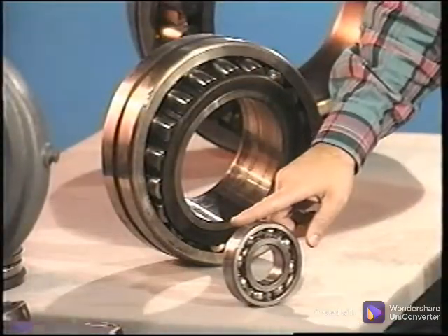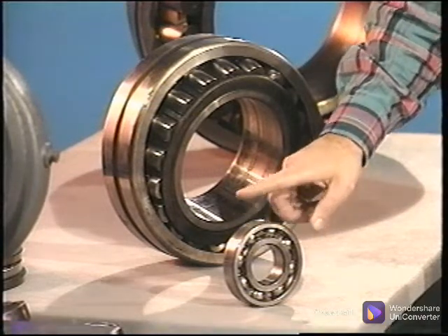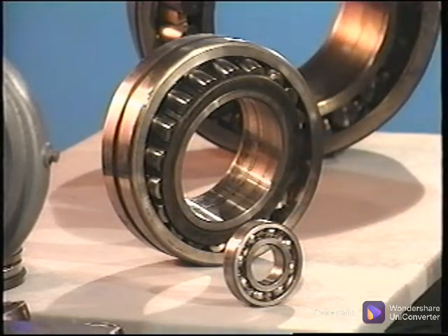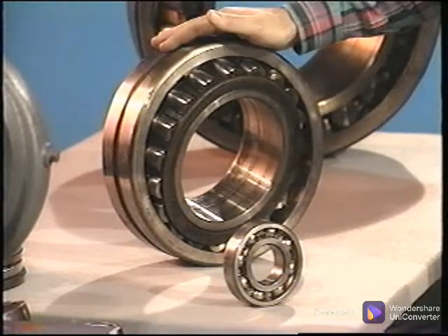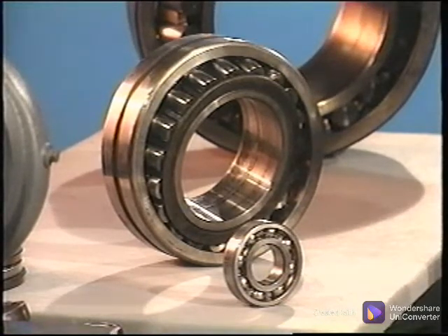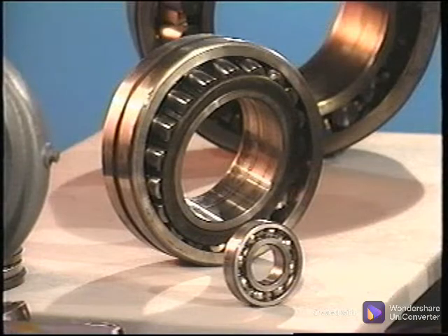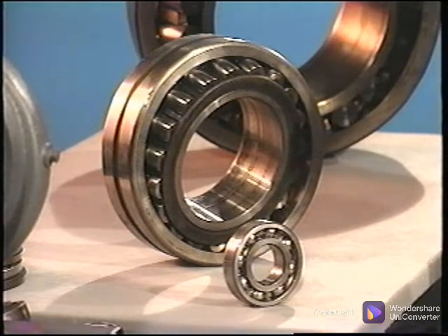This small bearing has 8 balls and has an inner race frequency of about 5 orders of turning speed. This means that defects could reasonably appear as high as 40 times turning speed. This bearing, on the other hand, has 19 rollers in it. The calculated inner race frequency is about 11 orders of turning speed. 19 rollers times the inner race frequency is 209 times turning speed.